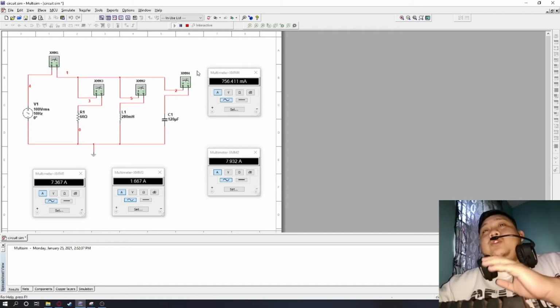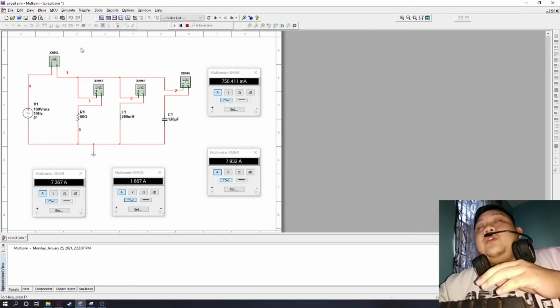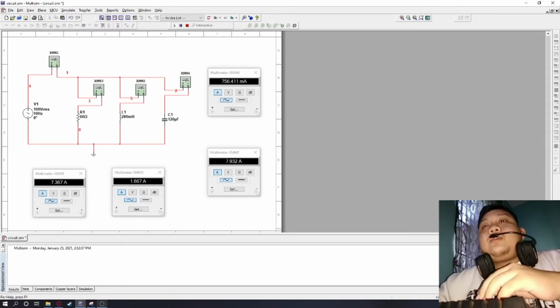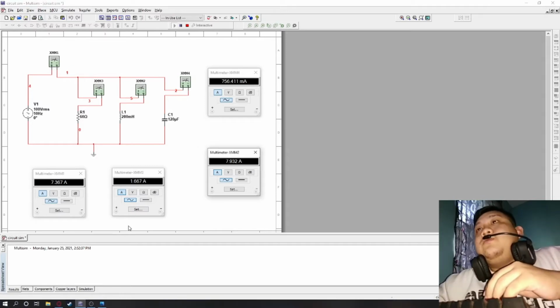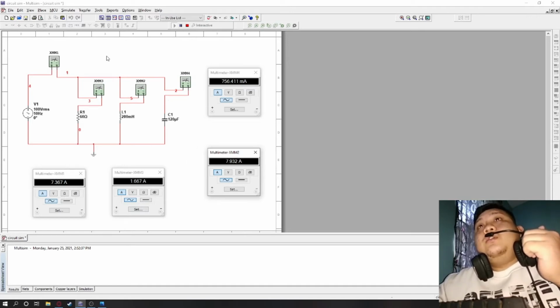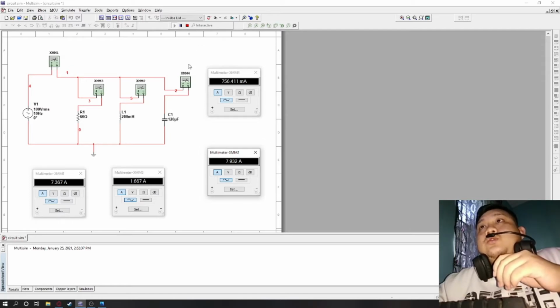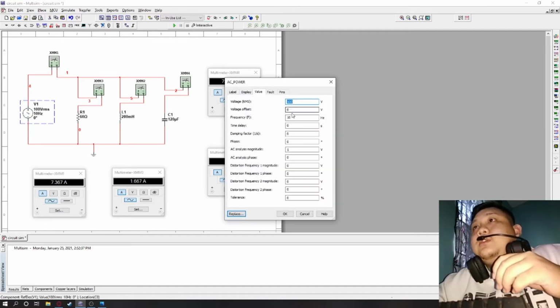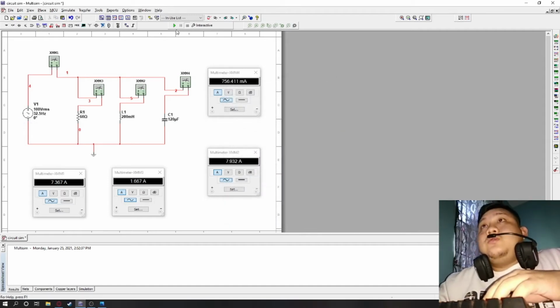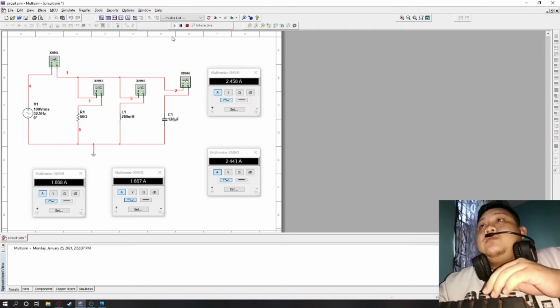So we're going to find out which frequency will make the circuit be in resonance state. We will use different values of frequency. I have shown the frequency from the calculation that Zaim has done. The resonance for the circuit should be at 32.5 Hz. So we'll see whether the circuit is in resonance state. We put here 32.5, and we're going to run the simulation.